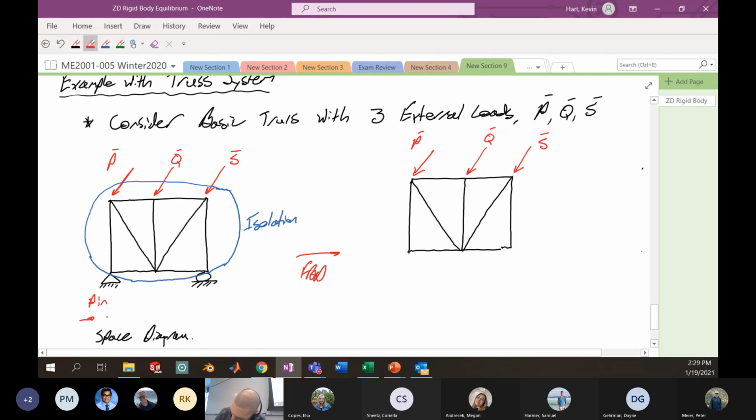And it has 2 reaction forces associated. That's that triangle with the dash there. So if I wanted to represent the reaction forces associated with a pin, I can do that with 2 forces that are orthogonal. And let's say that this is point A. I'll just make up some variable here. This is point A. So I'll say here that this is the force at A in the y direction. This here is the force at A in the x direction.